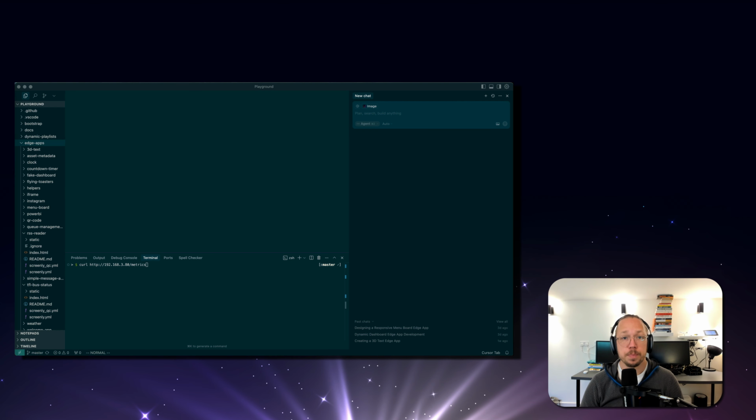What that means is that we're not going to use the REST API for ESPHome, which is the normal way you would get data from ESPHome. Instead, we have enabled the Prometheus endpoint on this particular device, which is basically 2 lines. You'll find that in the configuration that we'll link to in the description. So that's what we're going to use.